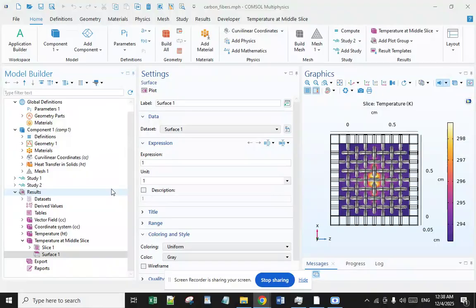The aim of this simulation is to determine the heat transfer properties of biaxial carbon fabrics of different architectures, including non-crimp stitch-bonded fabrics, plain, twill, and satin woven fabrics. The specific heat capacity was determined via DSC, or differential scanning calorimetry. A novel method of numerical analysis of temperature maps from a video using a high-resolution thermal camera is investigated for the measurement of the in-plane and the transverse